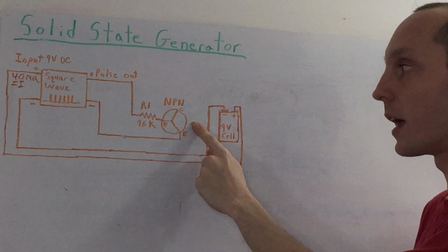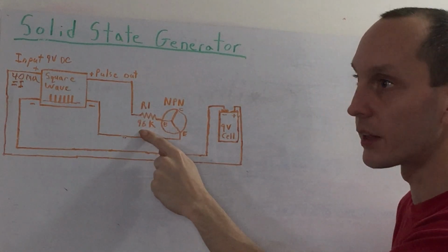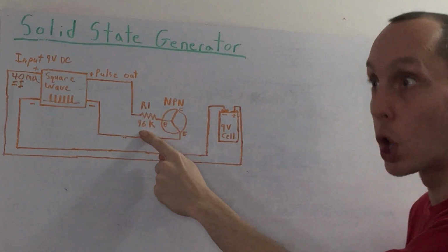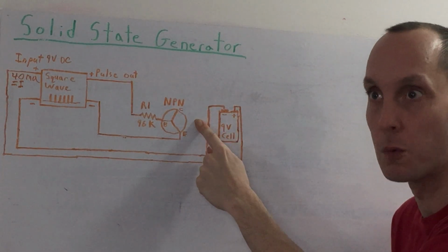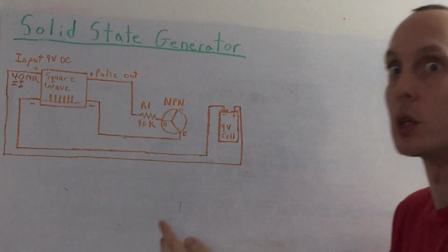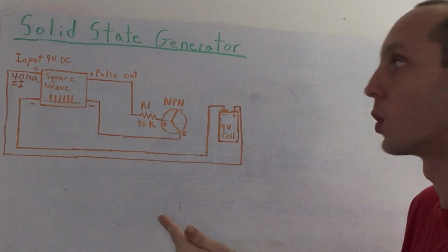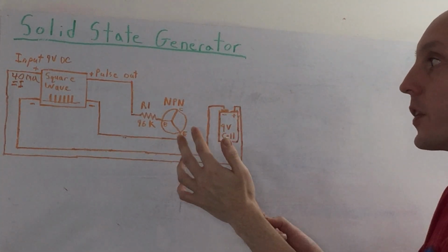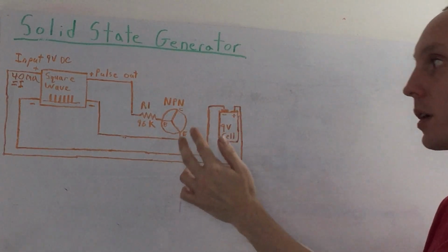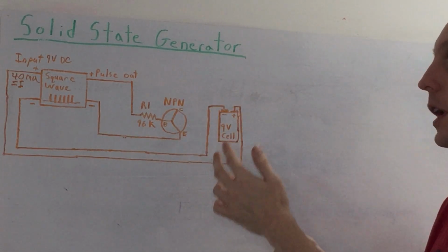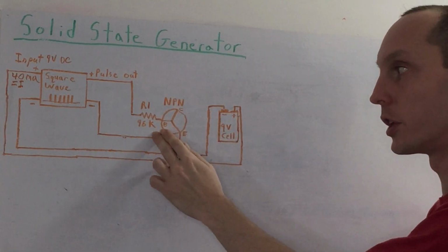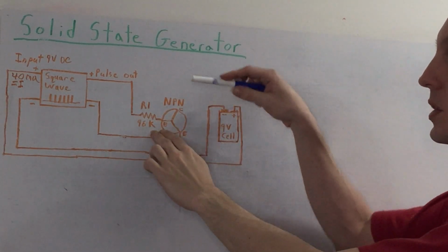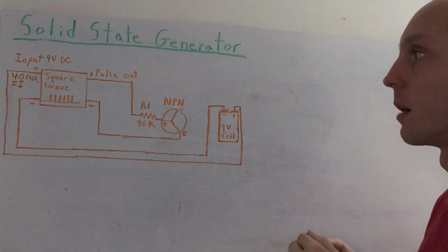On the other hand, if the resistor value is too low, we might be driving our transistor in oversaturation mode, which on its own will lead to a whole whack of other problems as well. So you have to really figure out the sweet spot of your transistor for a full on, without using too much voltage and without using not enough at the same time.